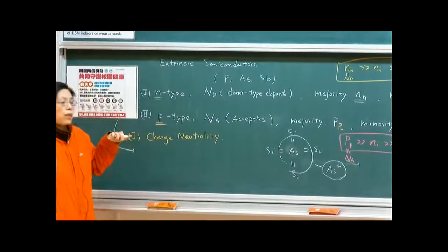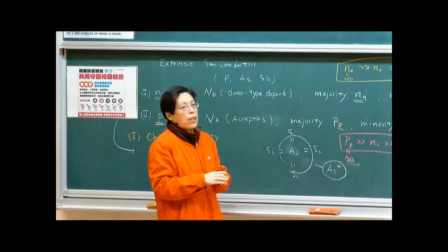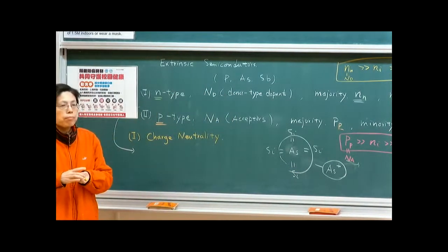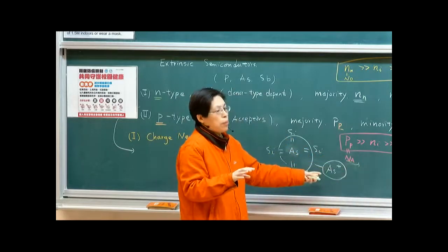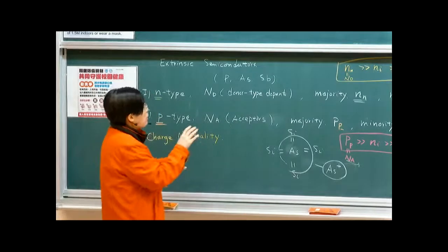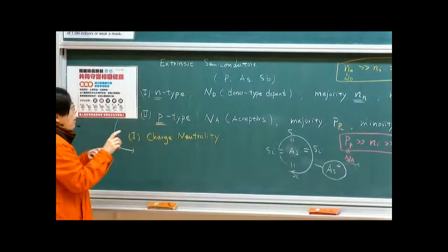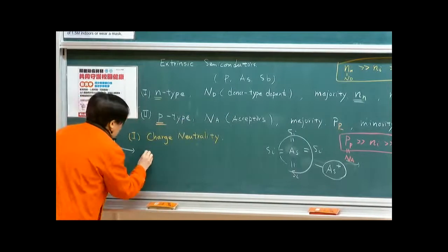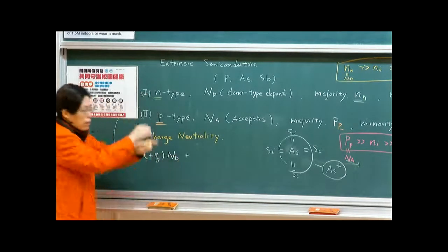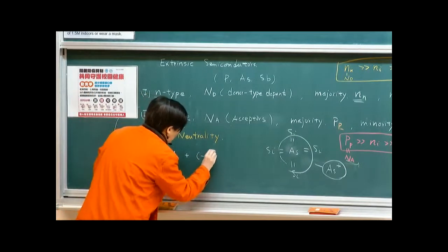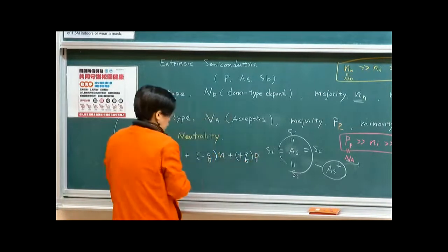It's supposed to be containing 5 valence electrons. One of the electrons left. Therefore, it will be a positively charged dopant. This is more like ionization. We call it ionization because the electron left, therefore it will be positively charged. So you have to think of the dopants: all of the electrons are donated into the system, therefore it remains positive charge. These donor type dopants will be positive, with charge q N_D in the system. And then there will be these electrons flowing around, which are negatively charged. So minus n plus another positive charge, holes p, plus q N_D equals 0.